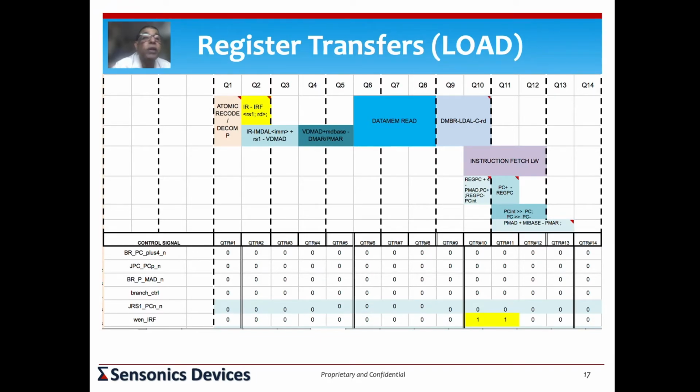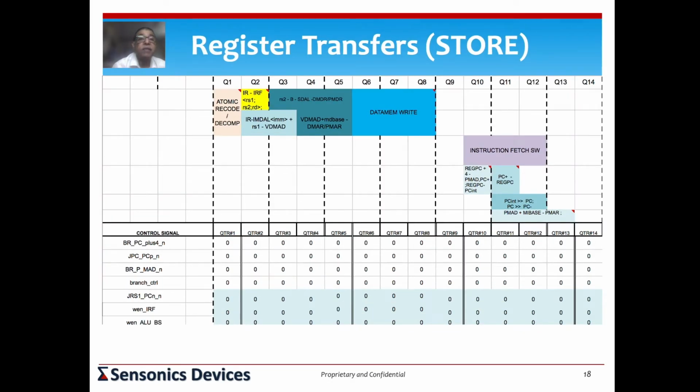So also true with each one of these other pieces of logic that we've written, excepting for a data memory read, which may not happen every cycle, unless there is a requirement through a load or a store, or an ALU operation, which would probably happen every cycle so long as you're doing computation. But when you're doing a load, at that time, the ALU might not be used for one particular bubble of a 4-cycle window somewhere. And now let's see the next one. This is a store, more of the same, and similar kind of a description as you can see here.